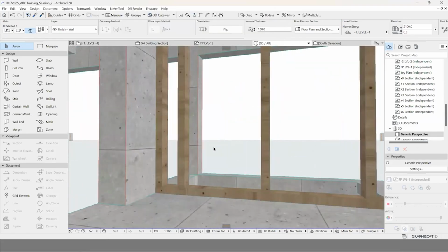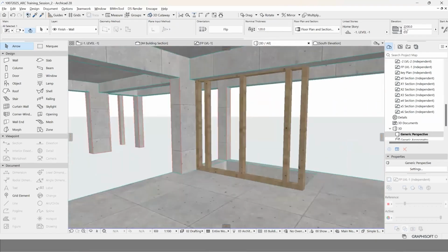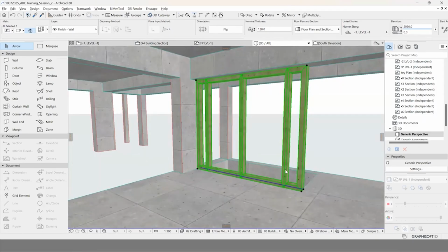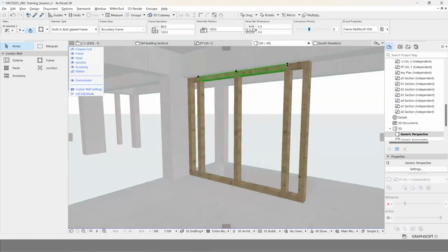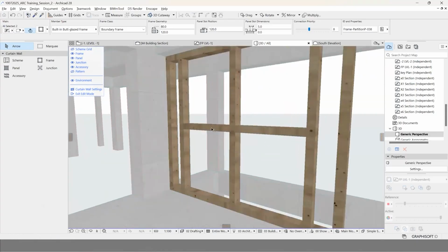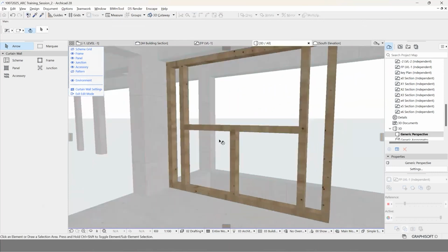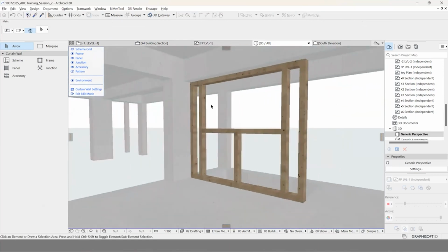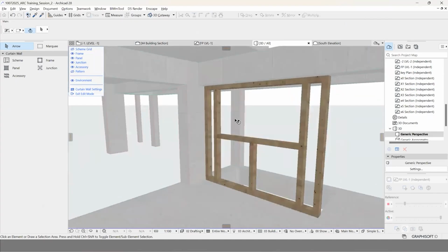The only thing that is missing is we have a centerpiece. So for that, again, I will go to the edit mode. So it gives you a lot of freedom. I can select these two and probably do a Control-Shift-3 to make a copy. And whatever the dimension is, I can just move it all the way down and it creates two different segments here. Now, if I delete the center, you can see this is what we want. Same option. So it's equally distributed from both sides and we just need to delete this option.